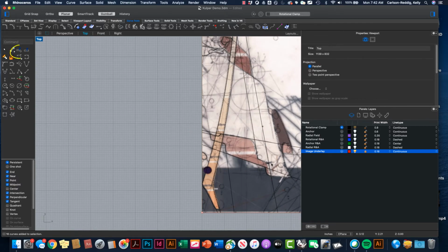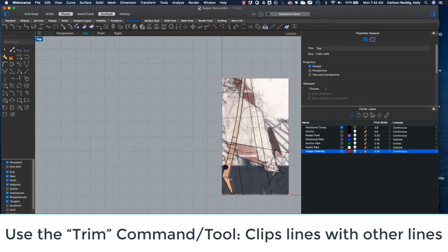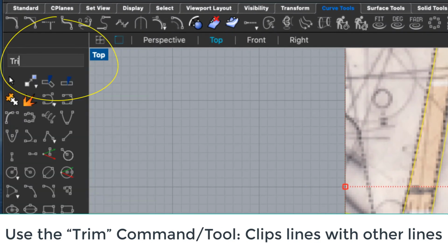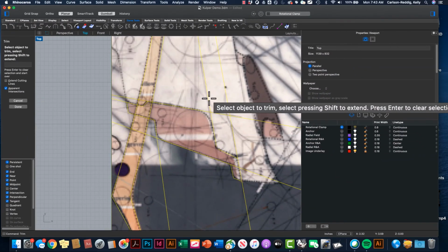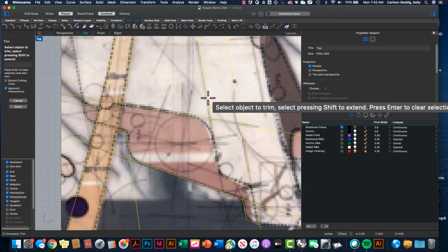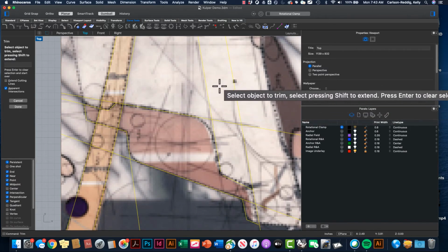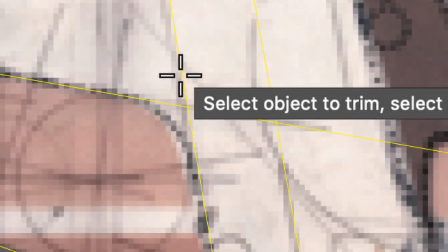Now a really good tool to use would be the trim tool. So let's go ahead and trim things. Select all my objects and type in the command trim. It's going to let me start editing off bits and pieces. So I can simply click on the pieces I don't want anymore. So these extended lines, they were really important as regulating lines. Now that I'm trying to construct this object, I'm going to want to trim them away.